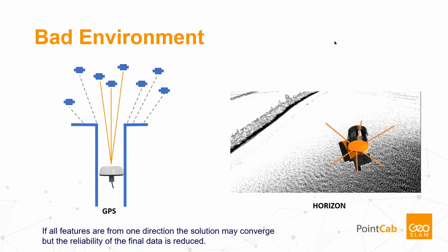This is something that people should have in mind as well, that sometimes the features can be behind you. For instance, if you're walking from one room through the hall, to improve the scan accuracy or reliability of your data, you can just keep pointing to the side where the system can see the best geometry of those features.